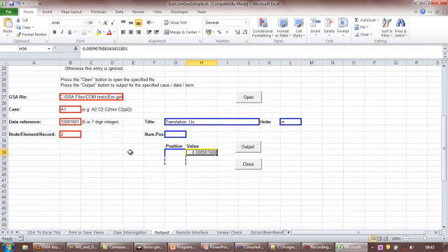The output spreadsheet, again, extracts output from GSA models. It demonstrates the use of the GSA output family of functions. So, let's delete all this again. It takes the analysis case and the node or the element reference, and it takes an integer, which is a 6 or 7 digit integer, which is the enum code for the result type that we want.